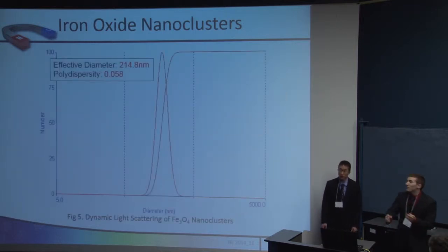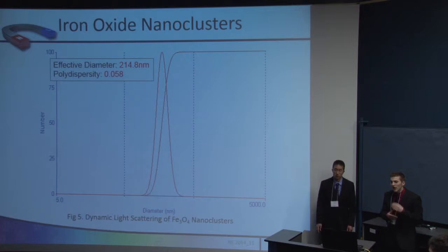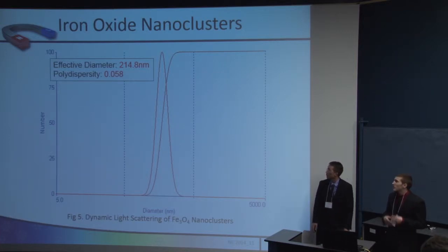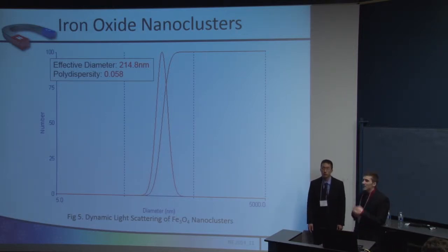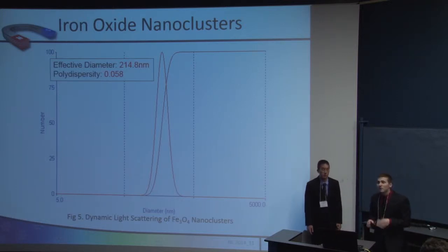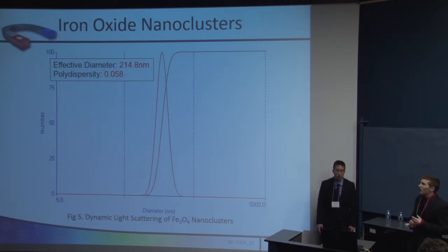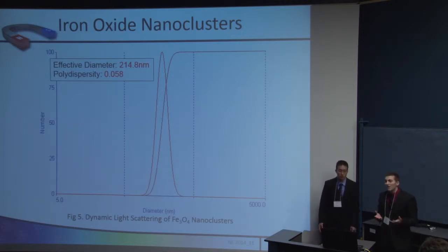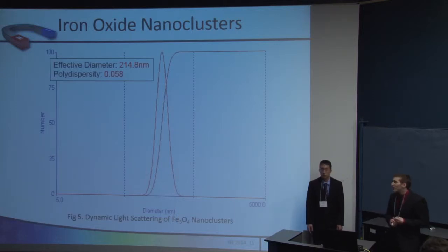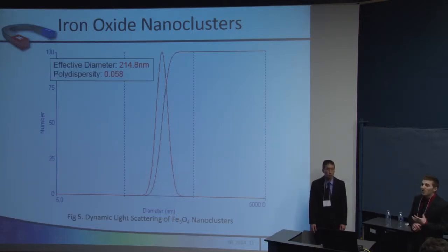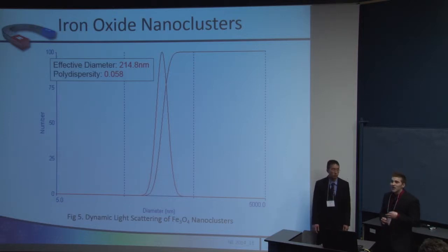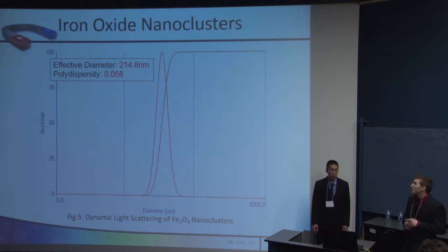So as part of these nanoparticles, a very important aspect of them is the size of the actual particles, because this will determine the surface charge as well as the interparticle spacing when a magnetic field is applied. So we measured our particles with dynamic light scattering, and we found that the diameter is approximately 250 nanometers. Now, 250 nanometers is above the ideal 140 nanometers to get the properties that we desire. However, we still see the phenomena enough to get an effective prototype.